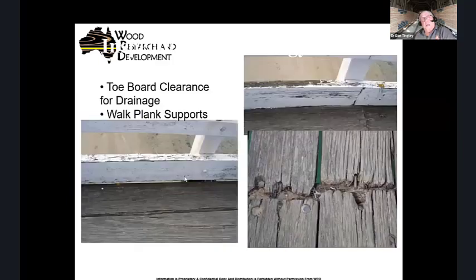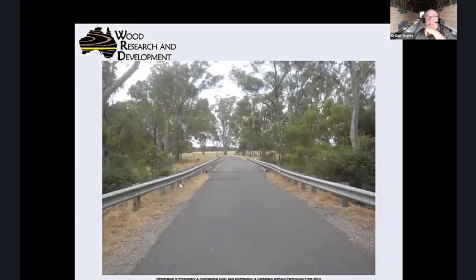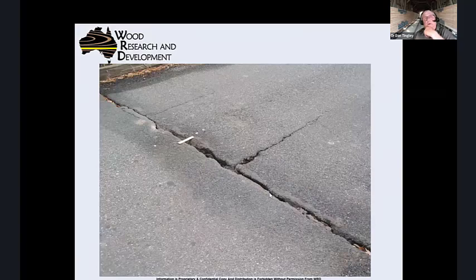And the kickboard was kept tight to the bottom, no drainage. You put it tight here, it decays. Open it up, it doesn't. This is the typical way things get done. Victoria, Violet, and here you see an engineer's called in. Here's a crack forming on the front of the bridge. You can see the ruler here, and they ask what to do, and the engineer comes in.